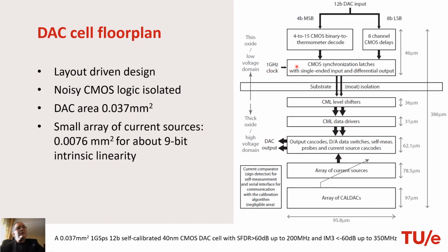The timing synchronization is done in the digital domain with thin oxide, low voltage transistors, so that it is very accurate. We have lower parasitics in thin oxide transistors, and we can have very accurate timing. Now, I already said the noisy CMOS logic is isolated.